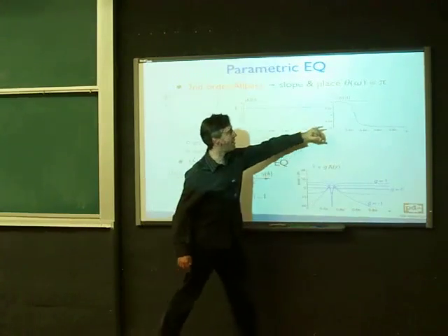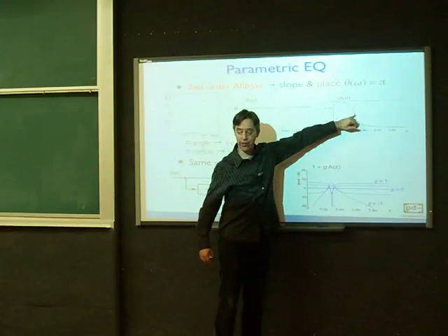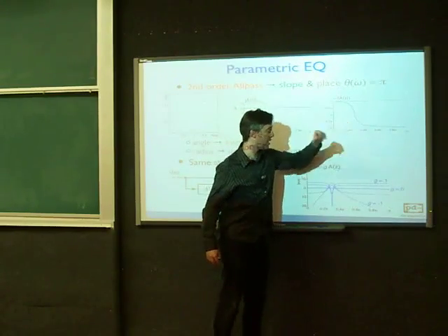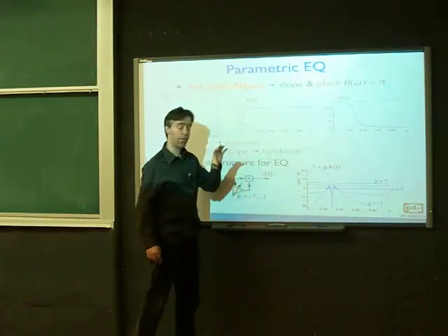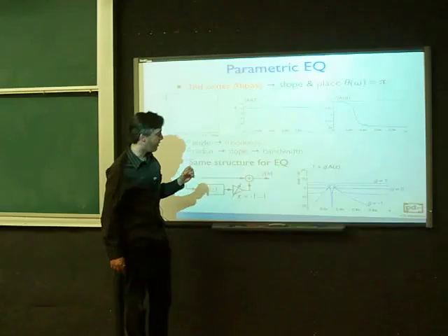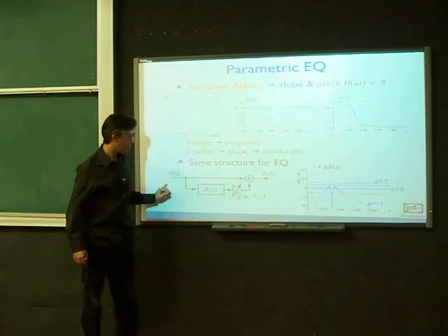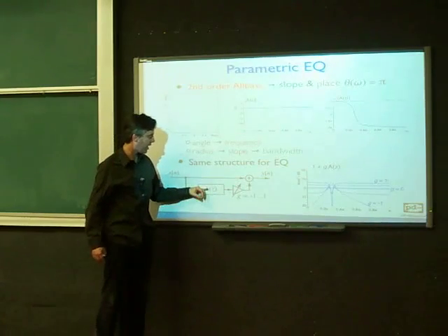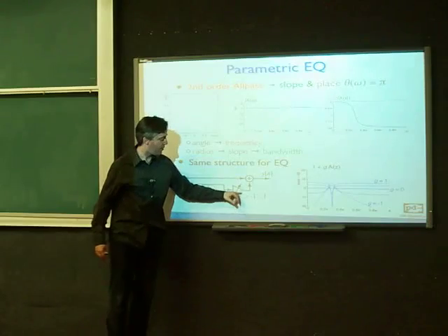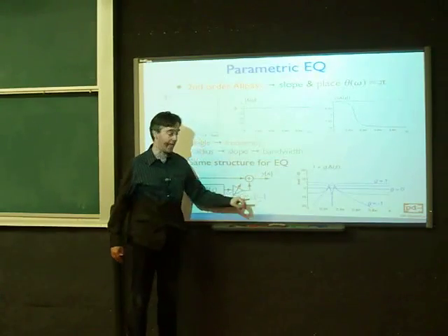So what happens is this is the point where you've got 180 degrees phase shift. And so if we add these two signals together, this is the point where we're going to get cancellation. And if we subtract them, it's the place where we're going to get reinforcement. So now we have a filter, it's the same structure, it's the same parametric filter, where it's taking this all-pass filter and then having a continuum between subtracting and adding it.